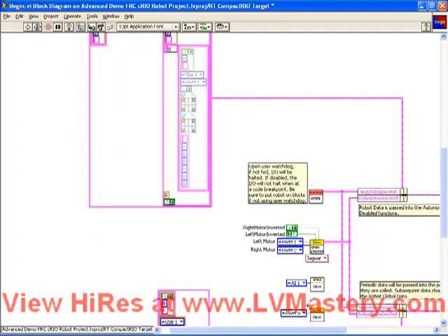So we've used these functions now to open up device references to the gyro and the servo. So if you remember from the basic robotics framework, we had to wire these device references into the main code so that we could use them for the gyro get and the servo set angle. And if you remember even further into the autonomous mode modifications for the basic, we had to put that data type into the robot global. By putting it into the robot global, we then made those device references available for the autonomous independent VI.